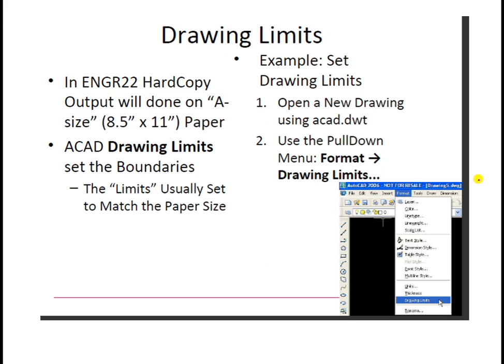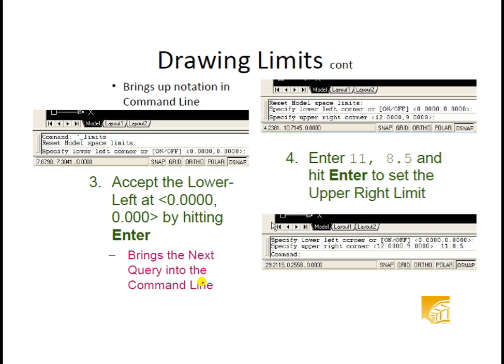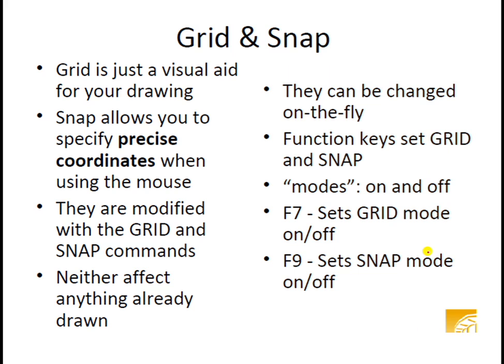So that can again be selected with the help of Format, Drawing Limits. It will ask you for the lower left corner, then give 0 comma 0 comma 0, and then it will ask you for the upper right corner, that is two zeros only because the third zero, that is the third dimension, is not available. And the upper right corner, it will be 12 and 9, it takes by default, you just have to do this.